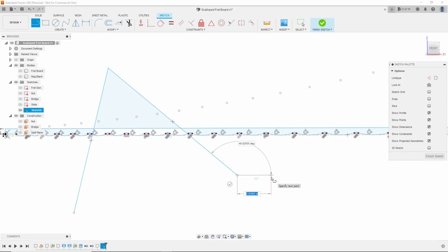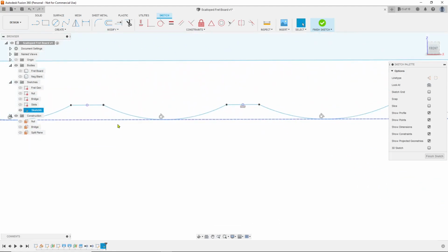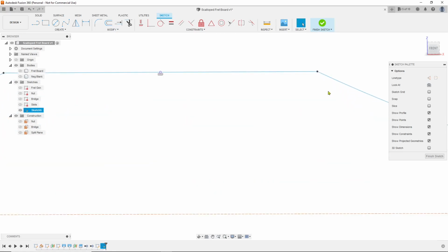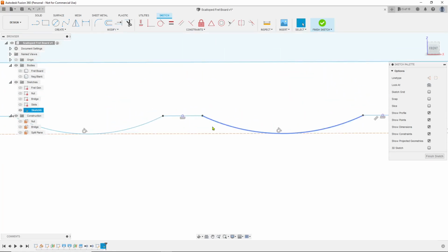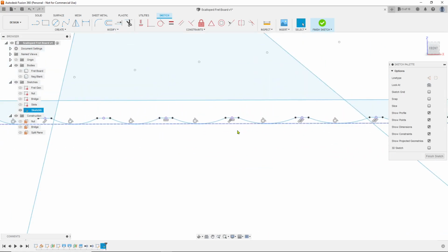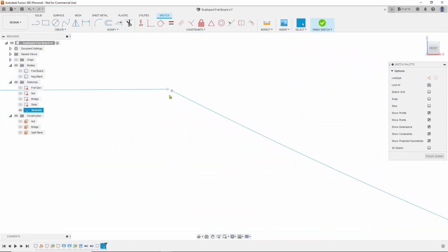So I can escape out of that tool, and I could just go on and on and on, running lines until I find where it doesn't close itself. So we scroll in here. Now we're looking for that little white dot. So it's a much smaller area to look for. Well, let's just do one more line right down the middle here, see how that goes. So now we made it even smaller, so now we only have to look at 2 places. And there she blows right there.